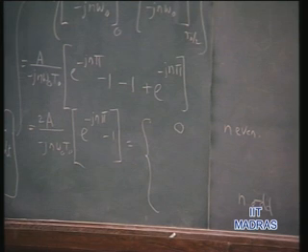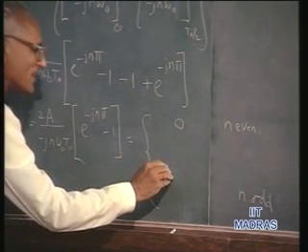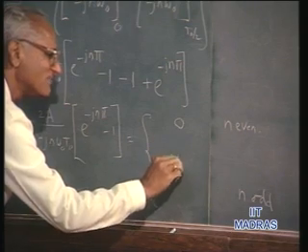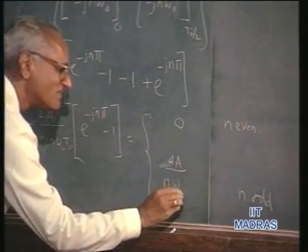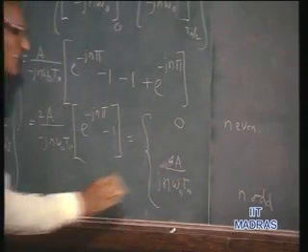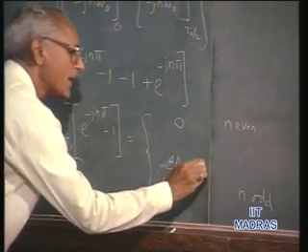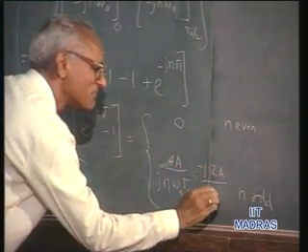So you have minus 2, minus 1, minus 2, and this j can be taken out, therefore this will become minus 4A divided by n omega naught T naught and a j in front, and omega naught T naught is 2 pi, therefore this will be minus j 2A by n pi.